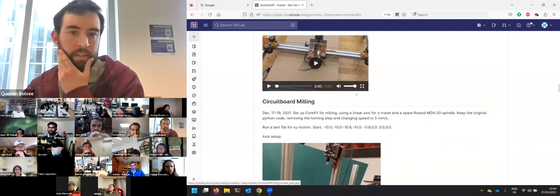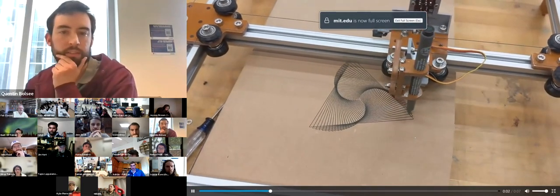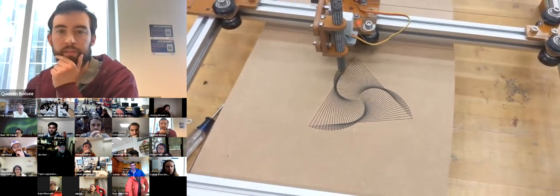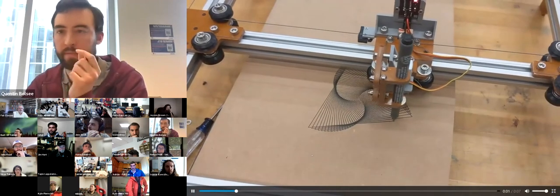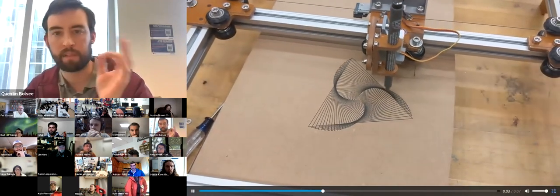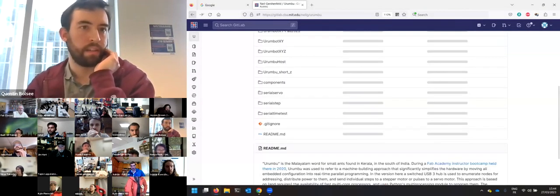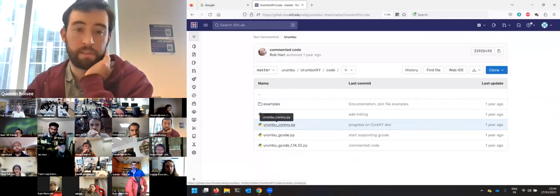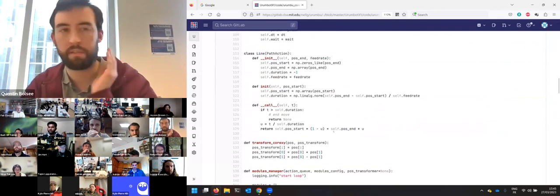And here's a test of the precision right here. This was kind of a surprise to us, that we could drive this whole thing from a Python process. Every single step that every motor is taking is 1 byte being sent by the Python process. The code is also available here if you want to have a look. It's Python, but really it could be any other language as long as you can send those bytes.